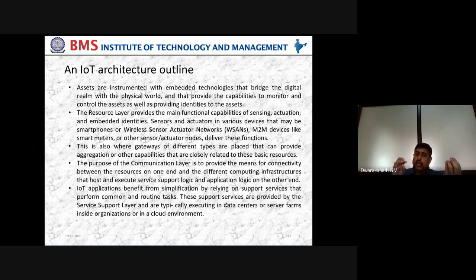Now, a lot of issues will arise in this communication layer. Last week, when we did a project with NodeMCU, it worked, but it was taking more time. When I press on, the relay bulb turns on, and when I press off, suddenly it doesn't turn off. Why? Because it depends on how busy your mobile network is, the network burst time, and the connectivity speed. Based on that, you have to connect to your server, and then connect to that particular device.